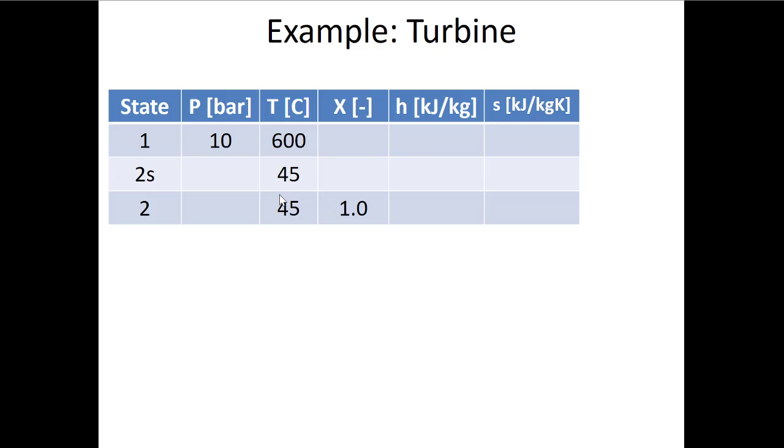So it'll usually have either the same pressure as the real outlet or the same temperature as the real outlet, because we want to compare what the ideal turbine power would be if it was operating between the same properties. They're not exactly the same states, but if we're reducing it down to a particular temperature, we want to know, okay, what's the ideal power we would get if we reduce that enthalpy, or that fluid, the steam, down to the same temperature.